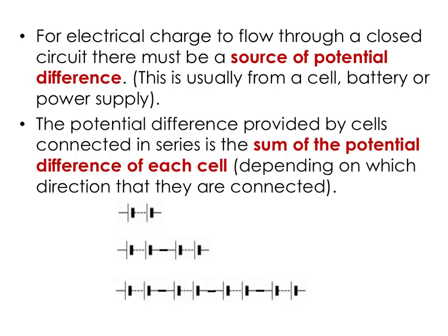Now the key thing about when you connect cells together is they have to be connected positive to negative. So you can see that we have the large side here. Remember I told you already that's positive, and the small side on this side is connected to the large side, and that's connected to the circuit. And we can see therefore that's connected correctly, and we will get an electric current flowing through there. The same would apply here because they're all connected in the same direction, but if we alternated that direction, then the potential differences of the cells would not add together.